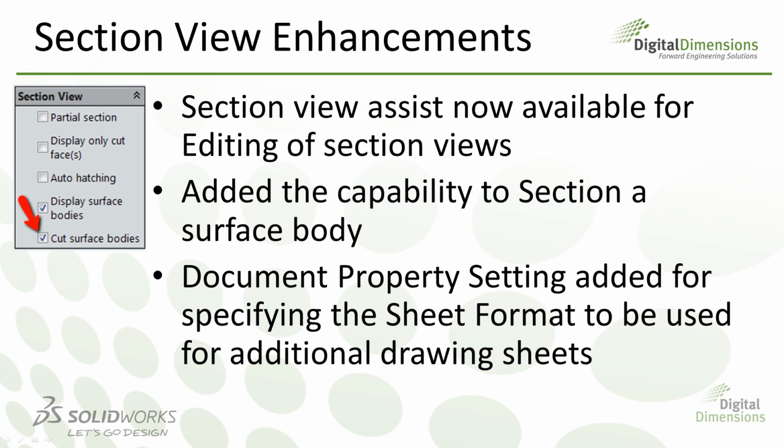But if you created this section view in 2013 using the section view user interface, in 14 you'll now be able to edit those section views with the section view assist. In addition to this, they've added the capability to now section a surface body.